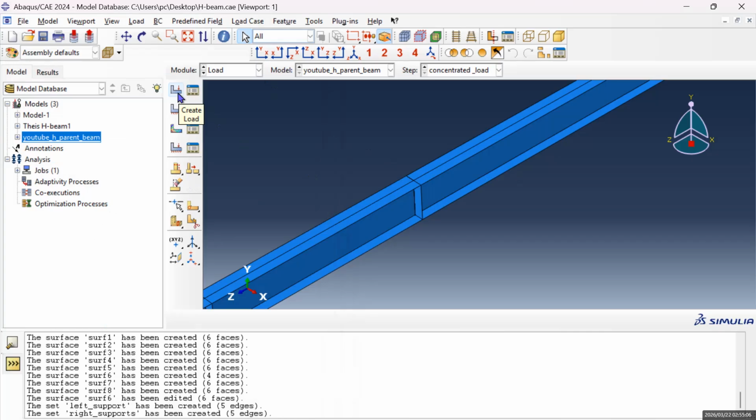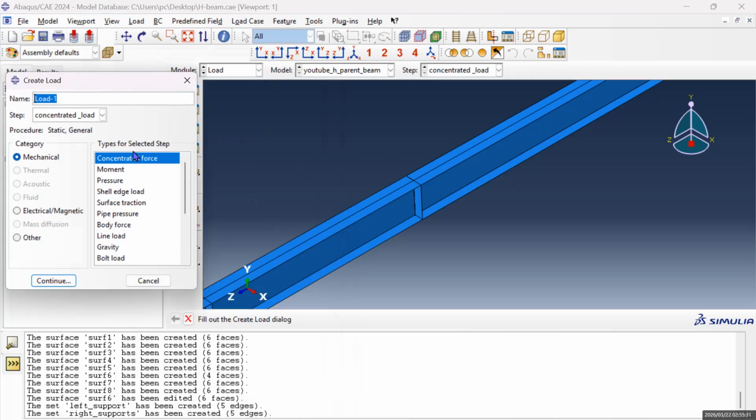The load that I'm gonna place in our project, we took 11.61, because at the distance of 37 millimeter is when we see the bearing capacity reach the maximum value. So I'm gonna take 11.61. So I will go here on the load, apply load.